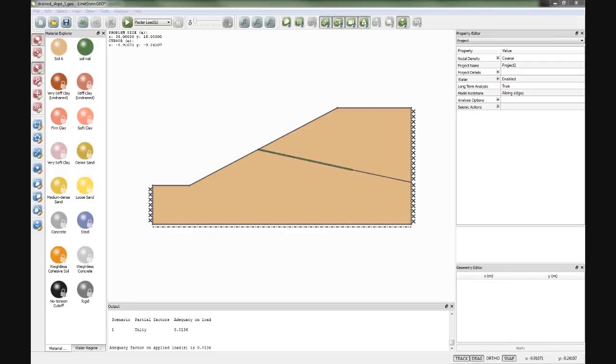Okay, I have a question. Do we have any plans to include modeling of progressive failure? And if so, what input information would we require? Essentially, the software, because it's based on the theorems of plasticity, is designed to analyze the ultimate limit state. So its power is its ability to go straight to the collapse mode using optimization, whereas in finite elements, you would have to increment up to that stage.